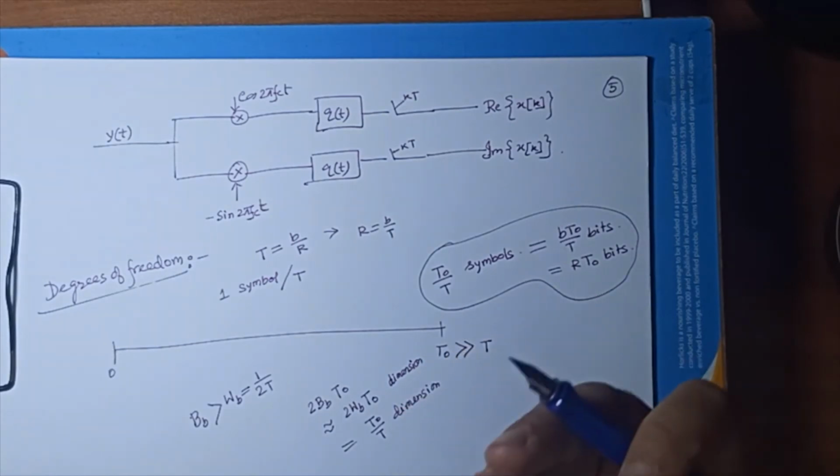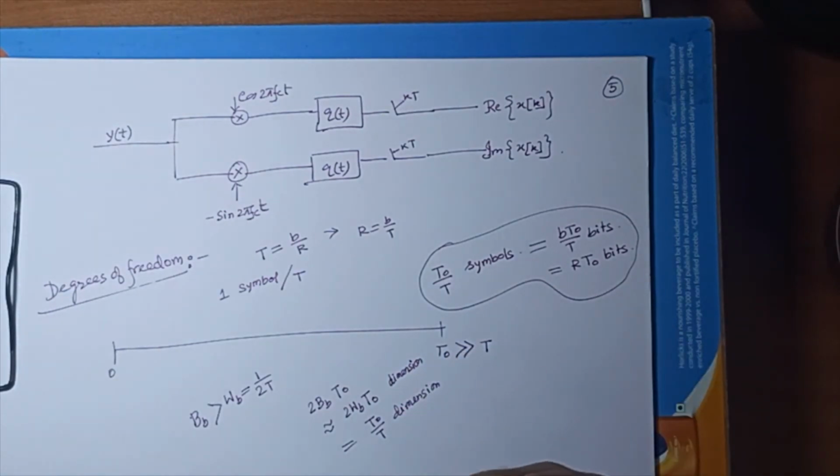So your efficiency basically depends on that alpha, the alpha of that filter design. You can see how things are connected. How much spillover in that spectrum you have in that low pass filter PT design is exactly the lack of efficiency in terms of the signal bit carrying capacity of this modulation method. Okay, so far so good. These are all good things.